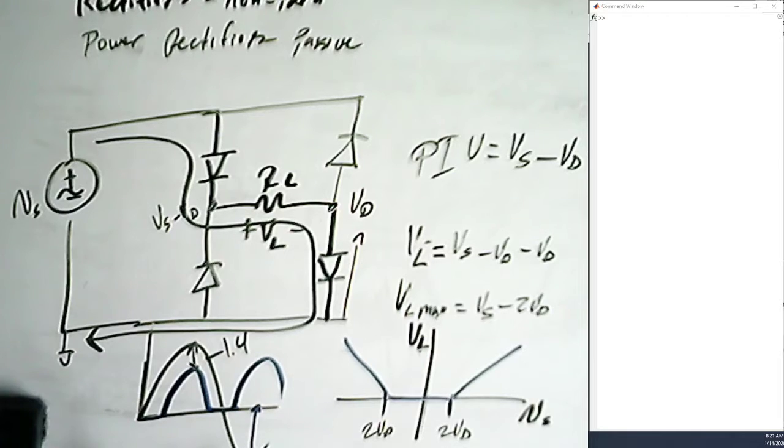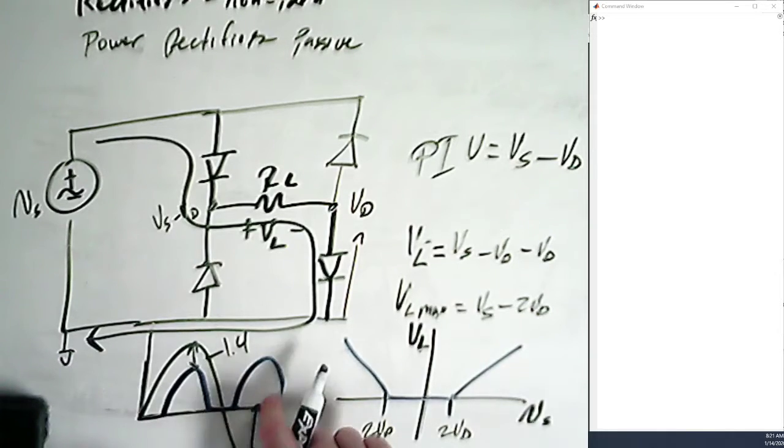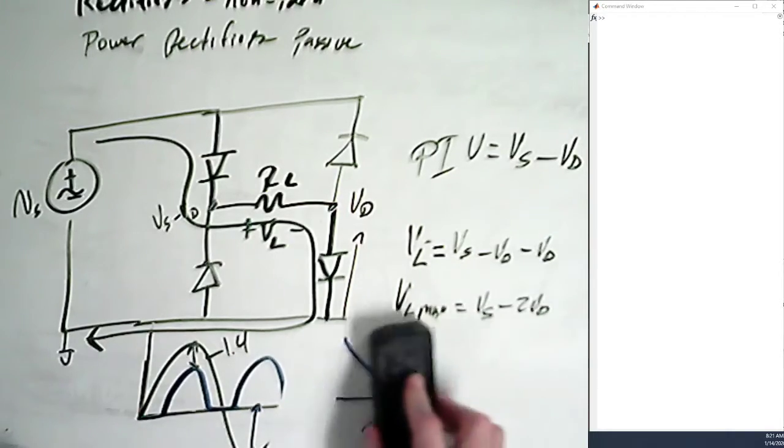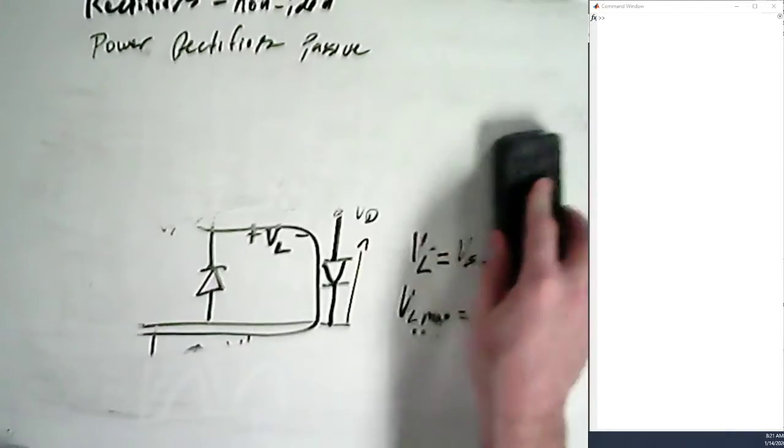And the rectifier is going to cause some problems. So there's some drawbacks to this. The drawback to the half-wave rectifier, not this one, but the other one, the half-wave rectifier with just one diode, is that we get half the juice through because we're missing half the cycles. Drawback to this one is that we are losing twice the voltage for the voltage drop over the diodes. And so that brings us to the transformer one.